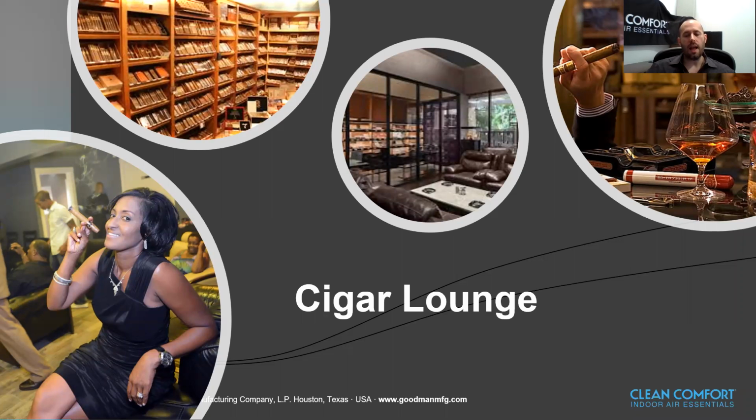Most cigar lounges rely on exhaust, and what I would say heavy exhaust. Now, in these applications, I usually add a HEPA unit or two. I'll add carbon filters and some purifiers. Now, usually I like to bring in fresh air where it's possible, but it's often outside the scope of what we can do. One other note with cigar lounges, it is usually not the cigar lounge that is complaining. It's usually the neighbors.